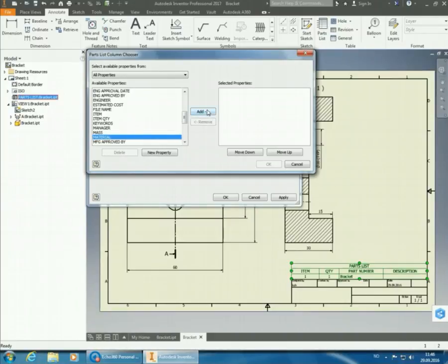In some cases, it might be nice to actually add not only material, but also this one named mass. Because as soon as you've set a material in Inventor, that material has all of the properties of it. So it also has the density. And from the 3D model, Inventor knows exactly how much volume it has. And coupled with the density, it knows the mass of the part. And that is nice if this is something that's going to be, for example, transported, and the weight is very crucial to it. For example, maybe it's a fairly small component, but it's going to be transported by helicopter to a rig or something. Then it will be very nice to know exactly what it's going to weigh. So then putting in the mass will be nice to have there. But in our cases, we're content with it just using material.